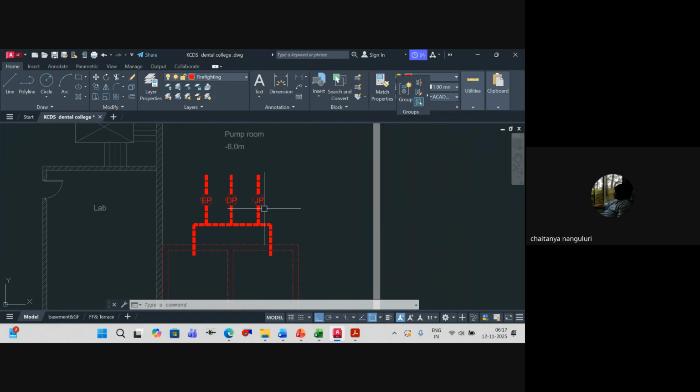So for lower flow rates, if there is one sprinkler leakage or someone has opened your first aid hose reel drum, you have very low leakages. In that case, first your jockey pump will come into picture. If the jockey pump is unable to handle the pressure drop, that means someone has suddenly opened the hydrant valve and the flow rate is very high, then your electrical pump will start running.